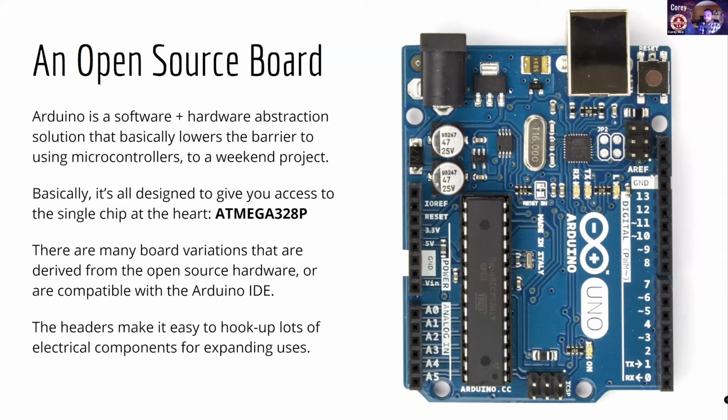This guy up here at the top is managing how power works with that chip. There's lots of different pieces and parts to the board itself, but basically an Arduino is just giving you access to a single chip. And that chip isn't going to be a full computer. It's just a little tiny microprocessor that lets you handle a certain amount of code, use it to run what happens with the pins that come off of it, and apply voltage or not, or read if there's a voltage or not a voltage. Fundamentally, it's all queued up so that this one little thing will work for you.